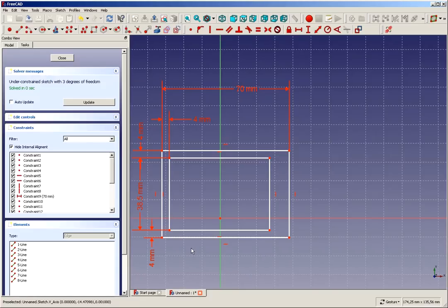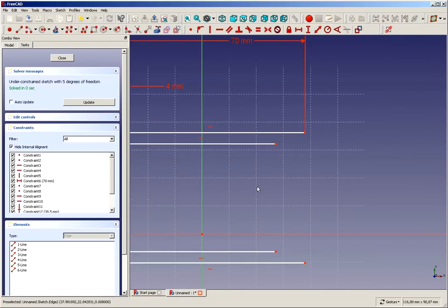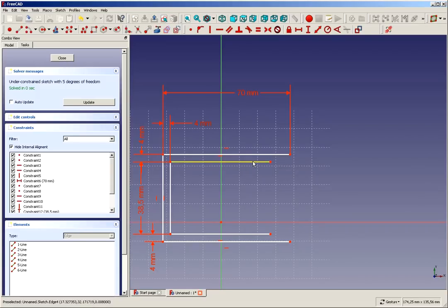Good. So the next thing is that we have to take away a couple of lines, which are these two lines. I select them and I take them away. In this case, we now know this should be the same length as this minus the 4 millimeters, and we do this again using a constraint, which is a vertical constraint of 2 points. Sorry, gotta click both of these, and now it's constrained that these both are over each other.